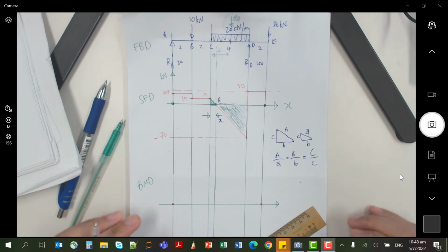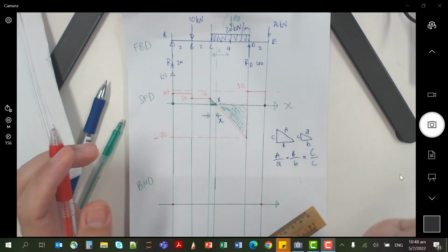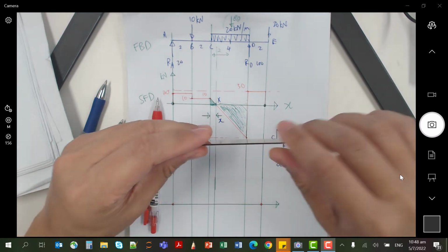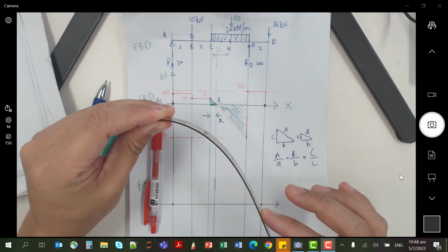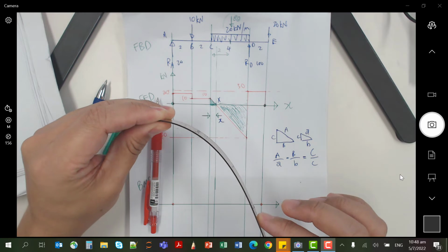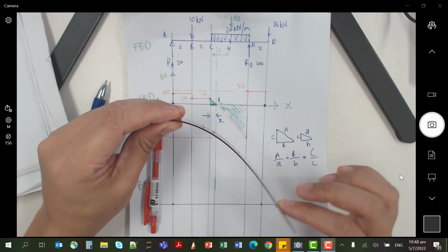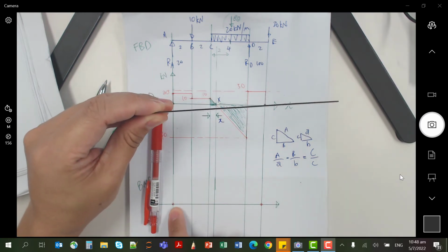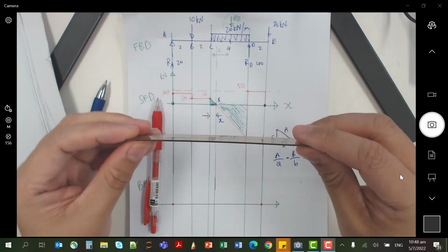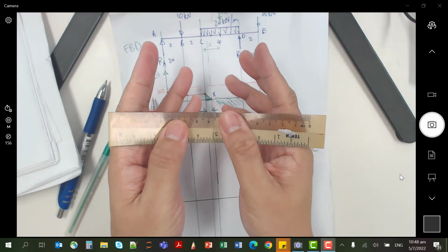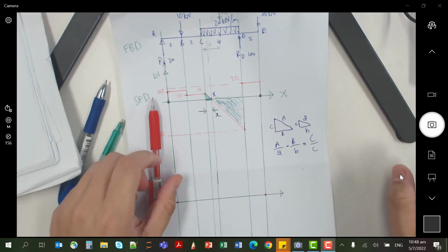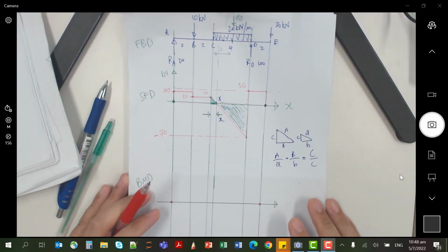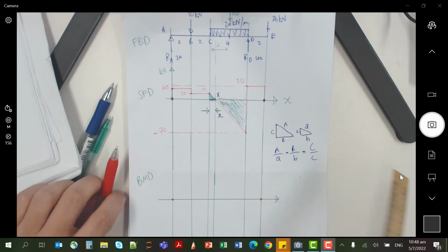Okay, but cantilever, again, it doesn't apply. Cantilever, because you are restricting the base. So for the ruler itself, it will feel that there is a bending moment at the base, so it cannot be 0. It's not like a simply supported or free end. It's free to rotate, so the bending moment is 0. Okay, so it's going to look like this.